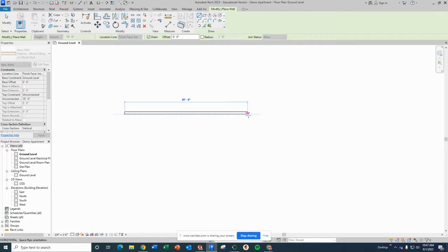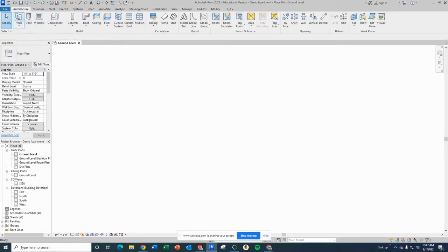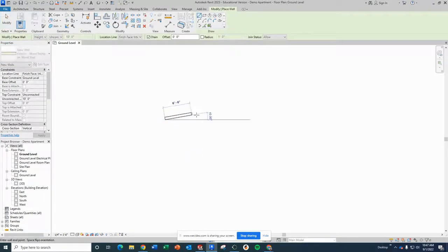We're going to use that tool here in a few minutes anyway, so I'll show you how to do that then. What I did is I clicked and released. I dragged out, and as you can see, when it's horizontal, there is no angle indicator, so that's how you know you're in the right spot. And now without doing anything, I'm just going to start typing 28 feet and push enter. And I just made a 28-foot wall. No, I did not. I believe I accidentally typed inches. So if that happens to you, you can undo back, get your wall tool again, and we will start over.